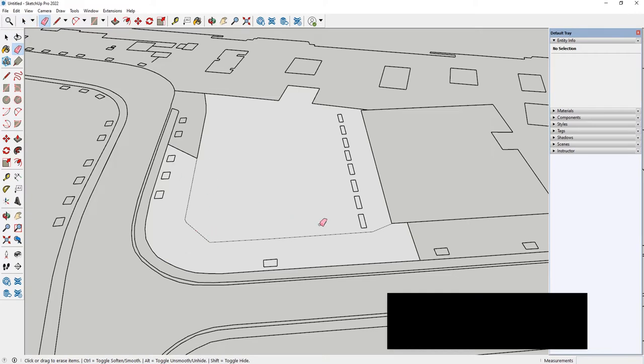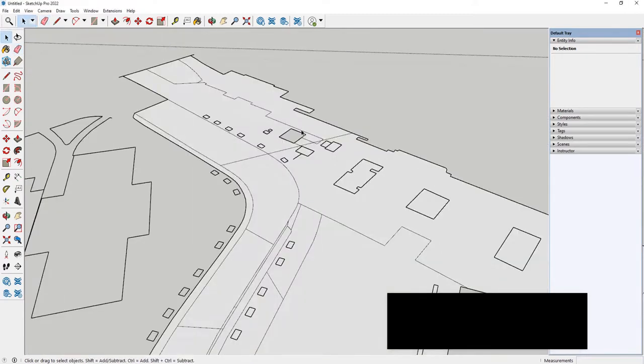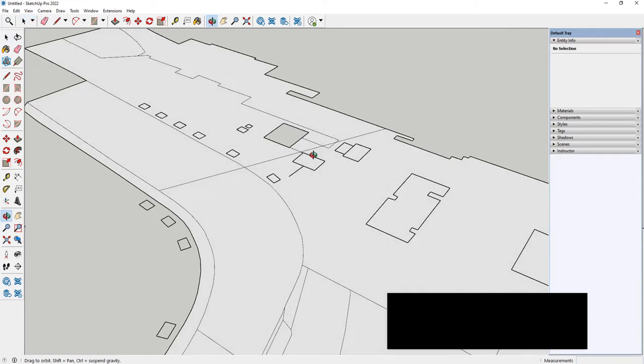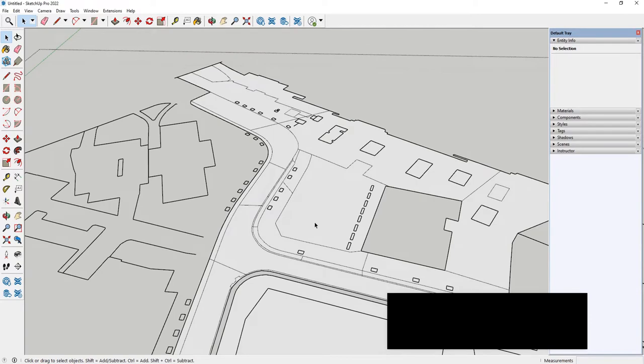And again, all we're really doing is taking these lines that we've imported from CAD and we're providing the extra boundary information with these little extra line traces that are just giving SketchUp the information it needs to actually turn some faces out of all these lines. So again, with SketchUp, all it usually takes is using the line tool, tracing a piece of that existing imported geometry from CAD, and that's enough to nudge SketchUp towards crafting it into an actual face.